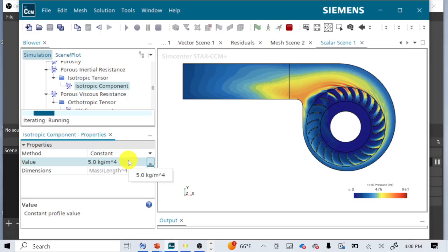We can change the flow resistance. If we just left this tube open, we'd have no way of changing that, right? It would basically say that your pressure left here at some value and then it entered here at some other. If we didn't have any type of resistance, we couldn't change delta P at all. It would just be stuck at whatever the heck it happened to be. If we do this, we absolutely can change it.